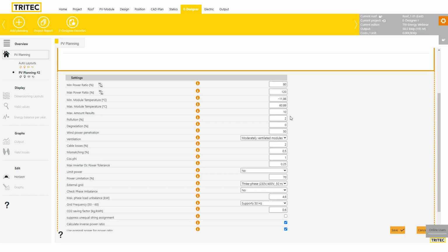So you certainly want to have the results on top where you use as few inverters as possible, plus the combination of the most efficient ones. If you're really trying to find the maximum efficiency, you probably end up with more inverters than fewer. But as I said, on the commercial side, it's not really desirable. So at least we try to find the combination of highest efficiency and fewer inverters. So 5 is good, 10 could be done. You enter a value of whatever you want.